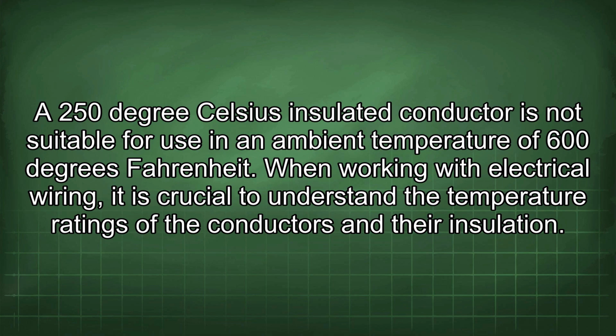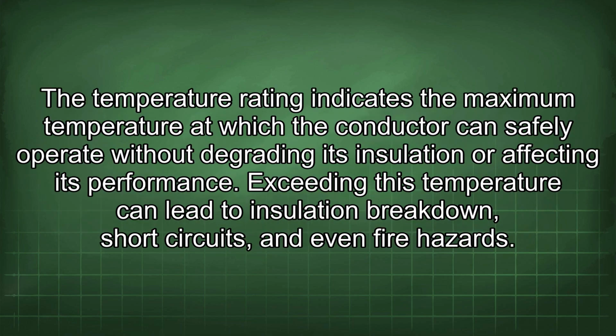When working with electrical wiring, it is crucial to understand the temperature ratings of the conductors and their insulation. The temperature rating indicates the maximum temperature at which the conductor can safely operate without degrading its insulation or affecting its performance. Exceeding this temperature can lead to insulation breakdown, short circuits, and even fire hazards.